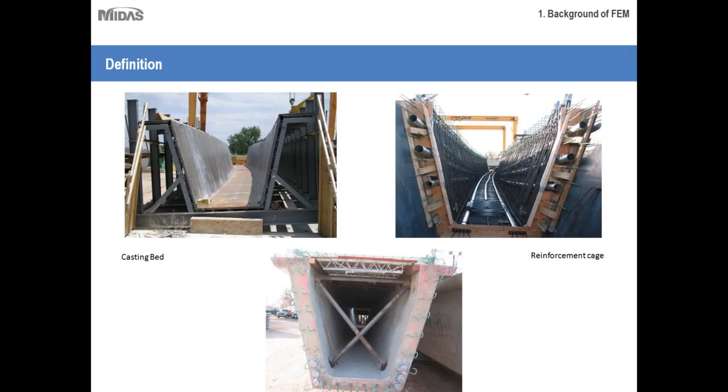The most popular type of construction methodology that resembles what I'm talking about here is balanced cantilever construction, where the segments are shorter in length and along a curvature, and the engineers erect one segment after another. But this section has somewhat revolutionized how the splice girders could be modeled.